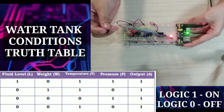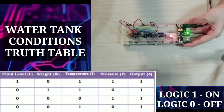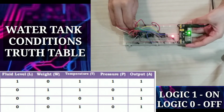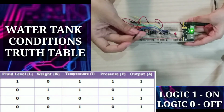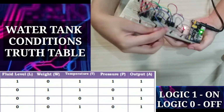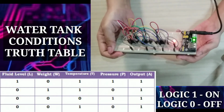meaning this white input here will be at logic 0, and if we have a low temperature, meaning the yellow wire here is at logic 0 as well. And lastly, if we have high pressure, or the blue wire here is at logic 1 on the other end, as you can see, our output will be at logic 1 as well, meaning our alarm system will turn on and the LED is at logic 1.